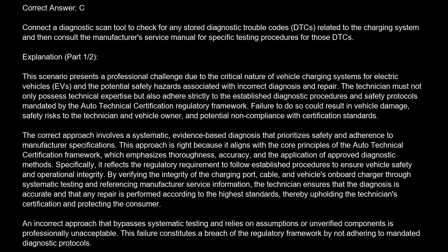The correct answer is C. Connect a diagnostic scan tool to check for any stored diagnostic trouble codes, DTC, related to the charging system, and then consult the manufacturer's service manual for specific testing procedures for those DTCs.